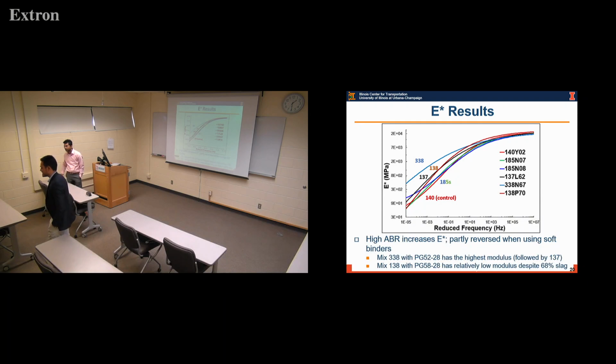But if we take the picture from the bottom, so this is the support and this is the specimen, and we put the camera this way, can't we check what's happening along the crack? We can look at what is happening along the crack lane, where the strain is initiated. That's something that can be done. What we need to come up with is different testing equipment.